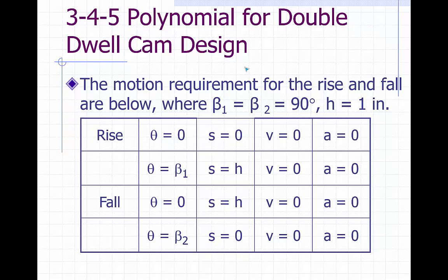This is part 2 of our polynomial cam design discussion. Here we're going to do a 3, 4, 5 polynomial for a double dwell cam design. Previously we looked at a single dwell design. So for this double dwell cam design we're going to use two polynomials.